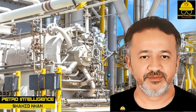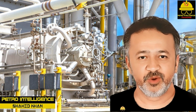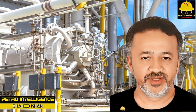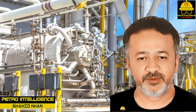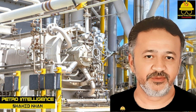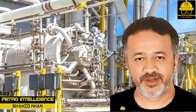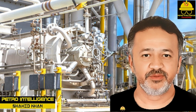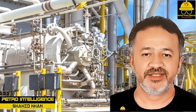Diaphragm compressors. Diaphragm compressors utilize a hydraulically pulsed diaphragm that moves or flexes to positively displace gases. This type of compressor is closely related to a reciprocating compressor. This type of compressor is a combination of several systems, a gas compression system and a hydraulic system. Gas compression occurs when a flexible metal diaphragm or membrane hydraulically flexes. In this type of operation, only the membrane and the compression chamber come into contact with the gas.